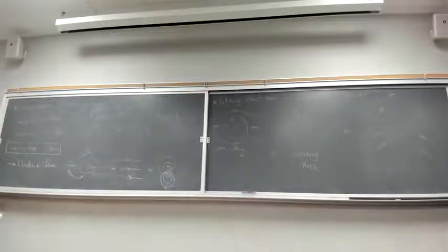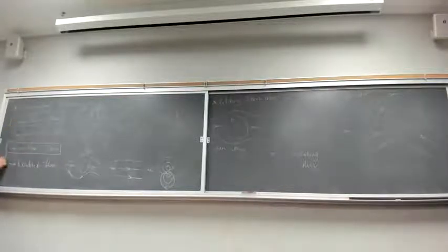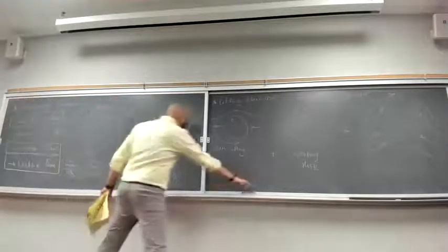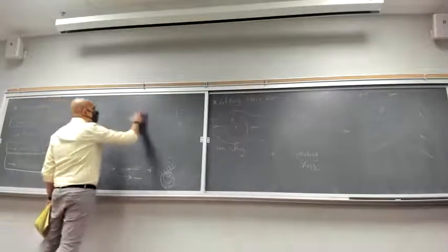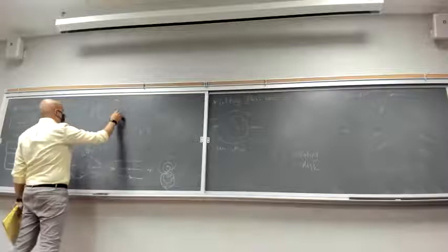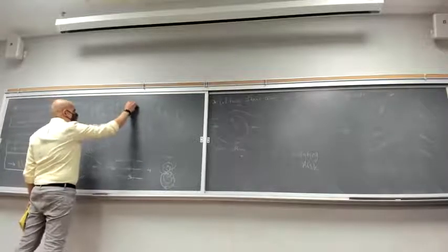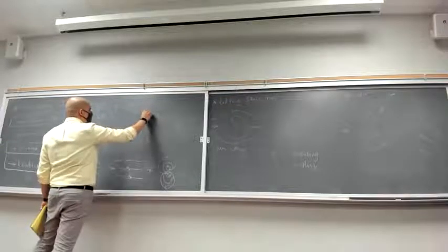So essentially a lifting flow over a rotating cylinder is a combination of your uniform flow, doublet flow, and the vortex flow. So the psi of LR is going to be psi of uniform flow, plus psi of doublet flow, plus psi of vortex flow.